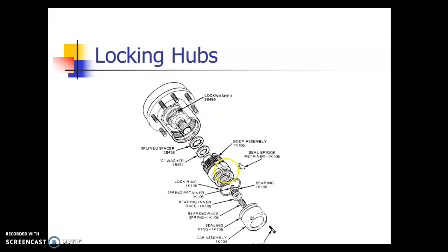So with the locking hub, you can connect it or select free, and that disengages the axle from the hub, so this hub spins free without turning that axle. And when you go to put it in four-wheel drive, you get out and you lock in the hub. Or what some people will do is when they're heading up to the mountains or going somewhere with four-wheel drive, they go ahead and lock this hub while it's convenient. That way when they get into the thick mud or gunk and shift the transfer case into four-wheel drive, you're ready to go. You don't have to get out and lock the hubs. So it's up to you. Again, it could be automatic, it could be manual. The computer can do it. In an all-wheel drive vehicle, they're just always linked. You don't get to disconnect them, etc.